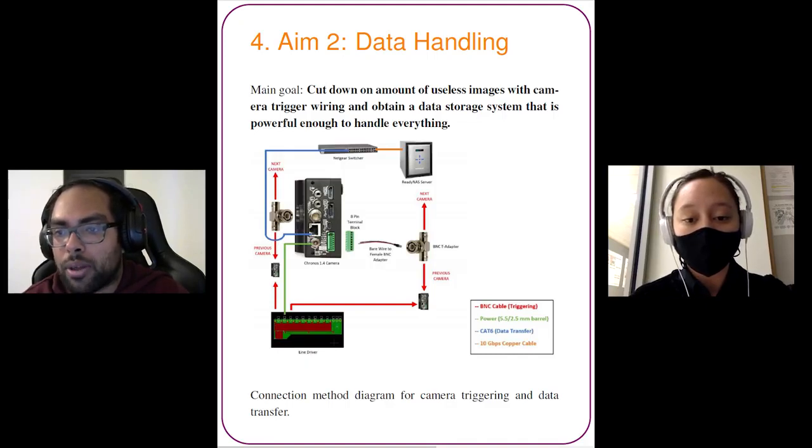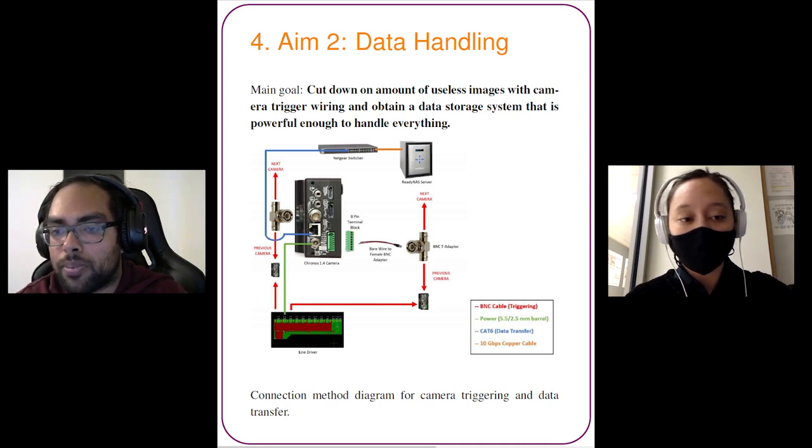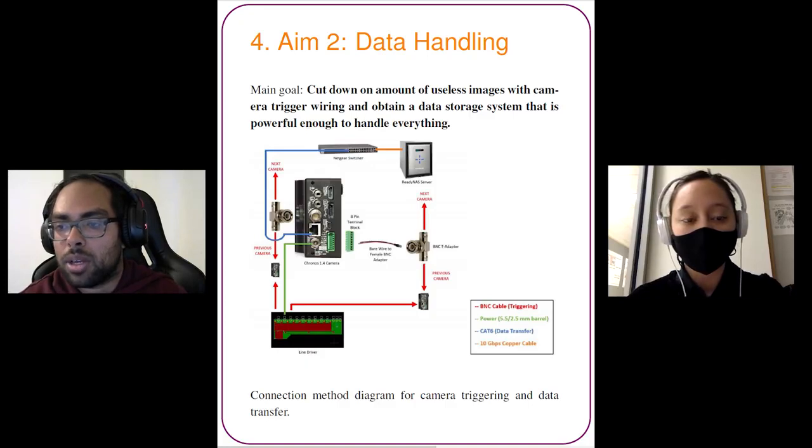Connecting the cameras together for synchronization, triggering, and data transfer requires the use of 3 connectors on the side of the camera, shown in the figure. Additionally, each camera will require its own power source, around 17 to 20 volts and 40 watts. Trigger I/O port 1 is a BNC female connector. This port will be used for synchronization of the camera frames. For the recording, there is somewhere between 650 to 959 microseconds between each frame.